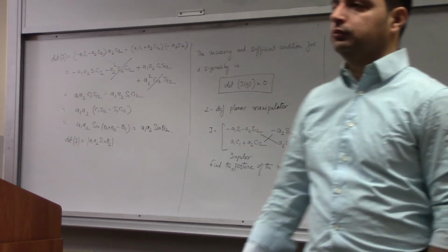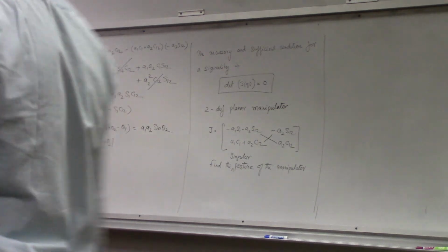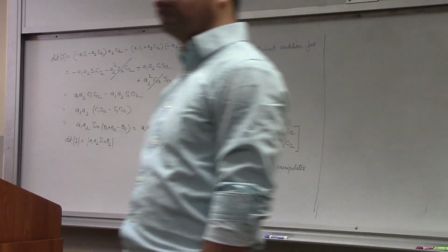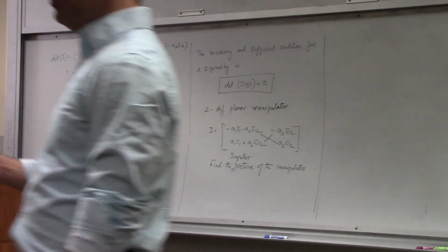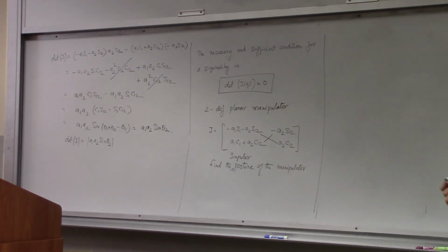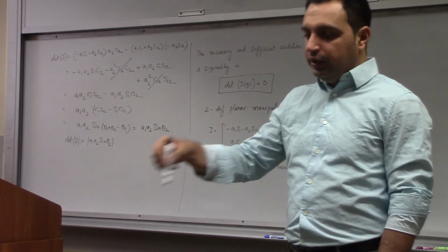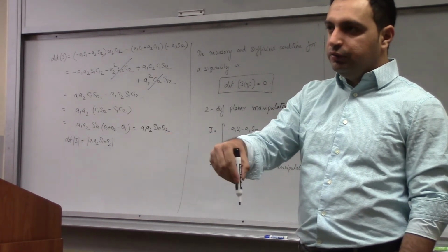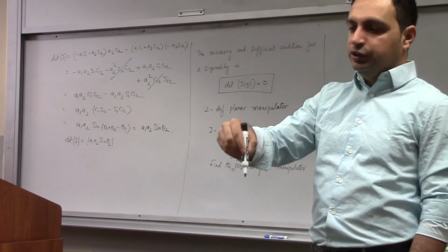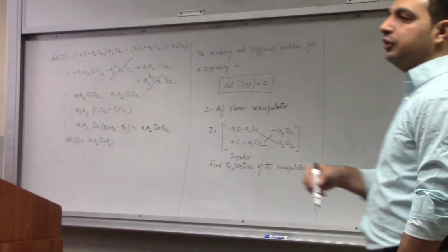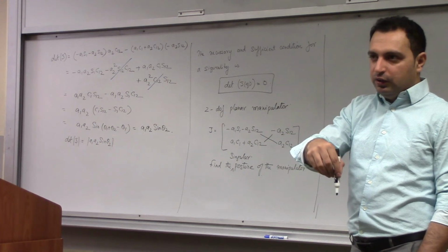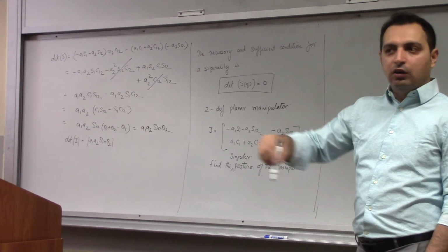Professor, why is the rank of a Jacobian important? Because it will tell you whether it's a singular posture or not. That's what I explained. When you are in a singular posture, you cannot move the manipulator in one or more directions. So when you're operating an industrial arm, if you happen to cross one of these points, you'll get stuck there. Because you can't move from that point in one direction. You have to move out from the other direction. So when you're path planning, if you get into one of these positions that you're unaware of, then you cannot move out of it.